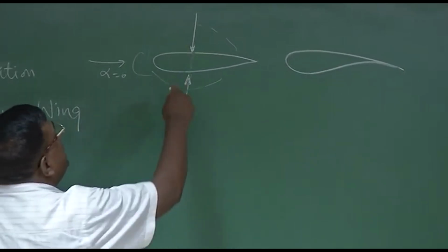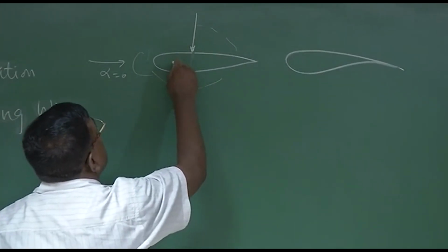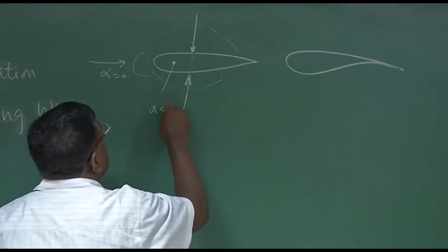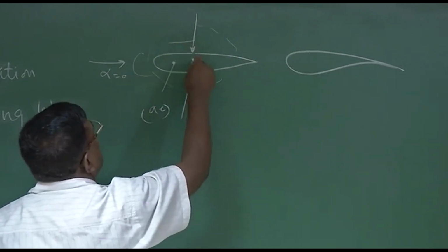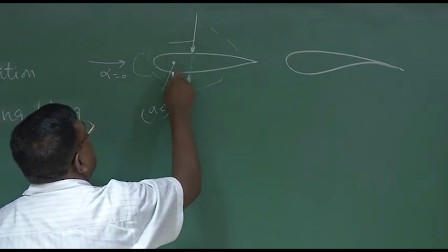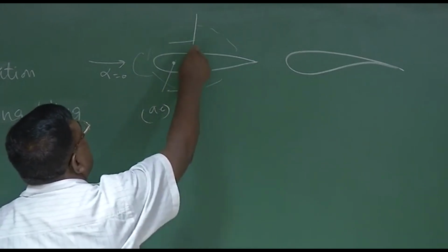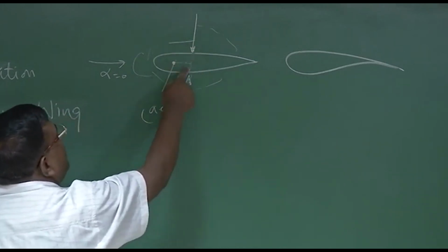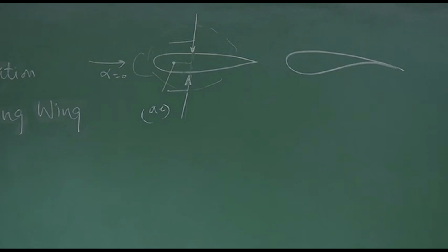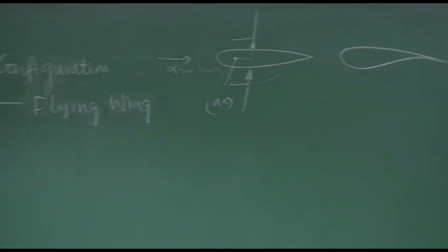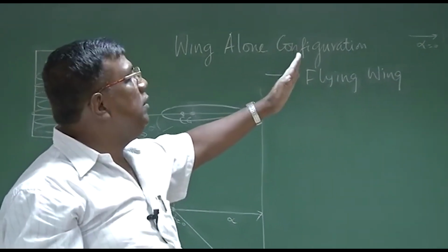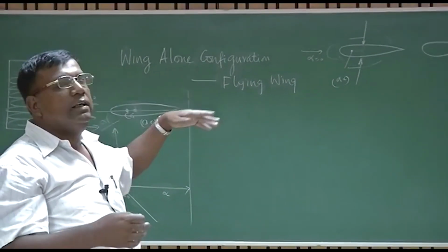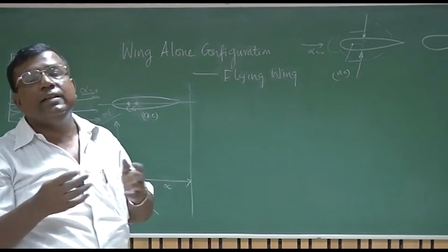So if I am transferring this whole force combination to the aerodynamic center, I have to transfer it by a force and a moment. This force comes here and a moment, and since they are opposite in nature and the same distance from this point, the net force or net lift will be 0, and all those moments which I need to transfer when moving a force from that location to AC are also in opposite directions, they cancel each other.